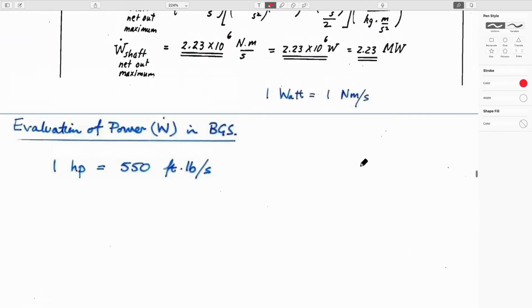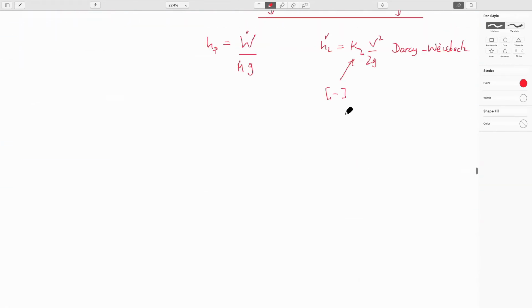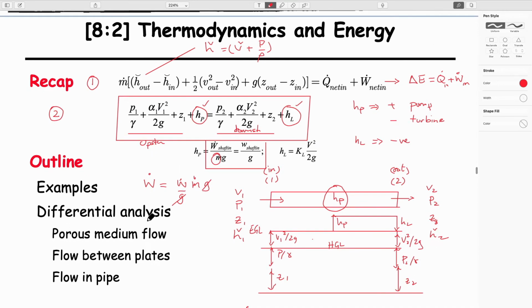So that's kind of what we'll use. To go back, all we're trying to do is account now for the fact that we have energy loss in the system. Primarily we'll use Bernoulli. It turns out to be a one-dimensional energy loss equation, Bernoulli with 2 extra terms added. One is a pressure head, one is a head loss. We have to be a bit careful about the sign conventions we apply to them, but apart from that, it really comes down to just defining the geometry.